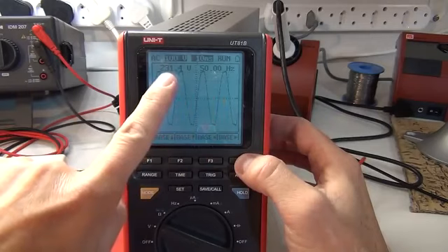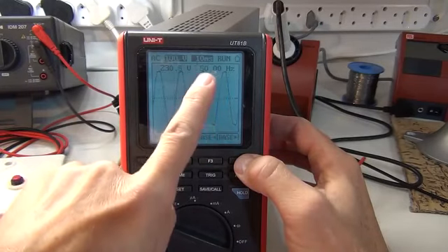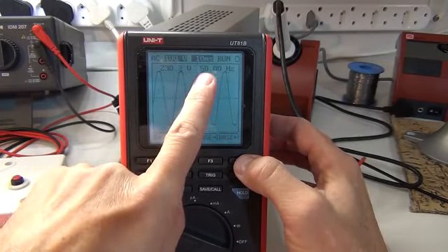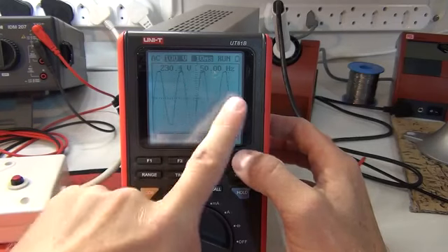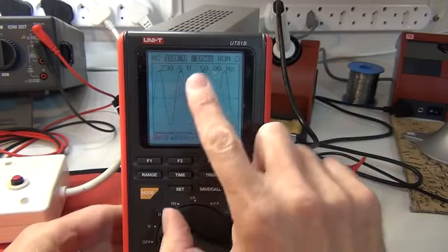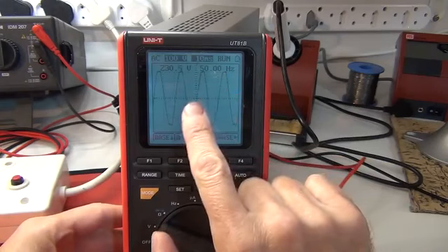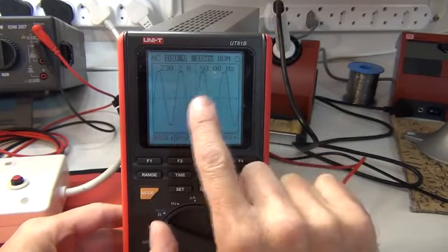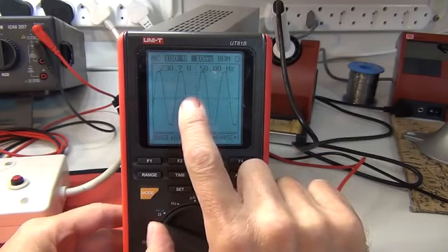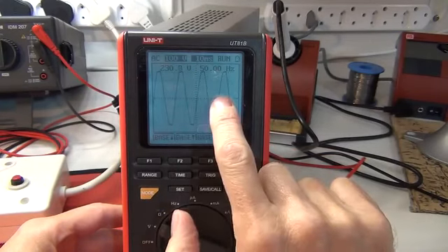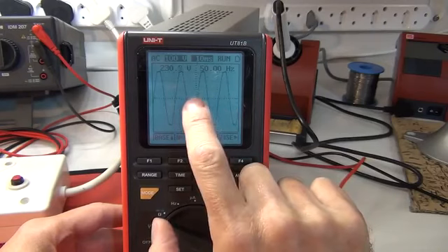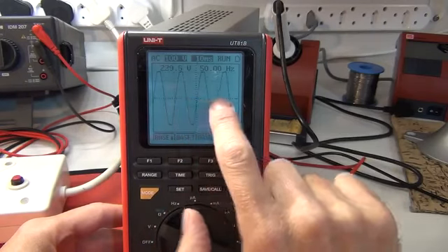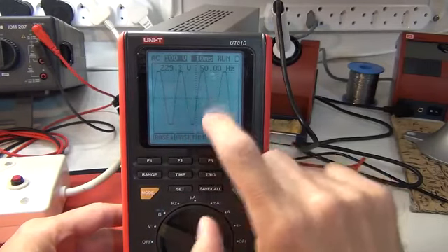And as you can see here, we've got the voltage and we've got the frequency, which here in South Africa is at 50 Hertz. On this meter, we've got this set to 10 milliseconds per division, and if you count the divisions where you've got a repeating cycle, there a cycle starts, that's half of the cycle, and then that's the completed cycle over here.